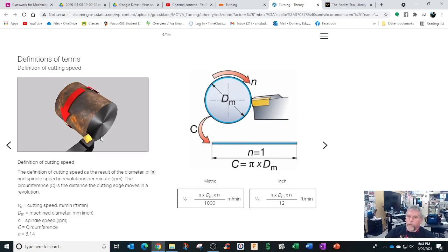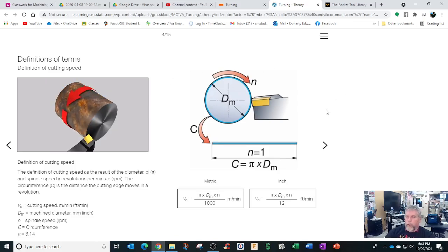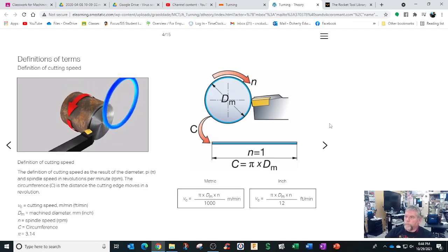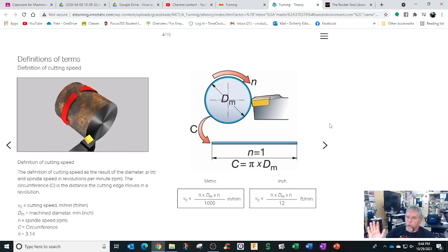So the first thing you want to know is RPM. A lathe can run in either RPM or constant speed, CSS. And in G-code, on most Fanuc or Haas lathes, or Fanuc-controlled lathes, you can switch from RPM, which I believe is the G97 mode, to the surface feet per minute mode, which is G96.